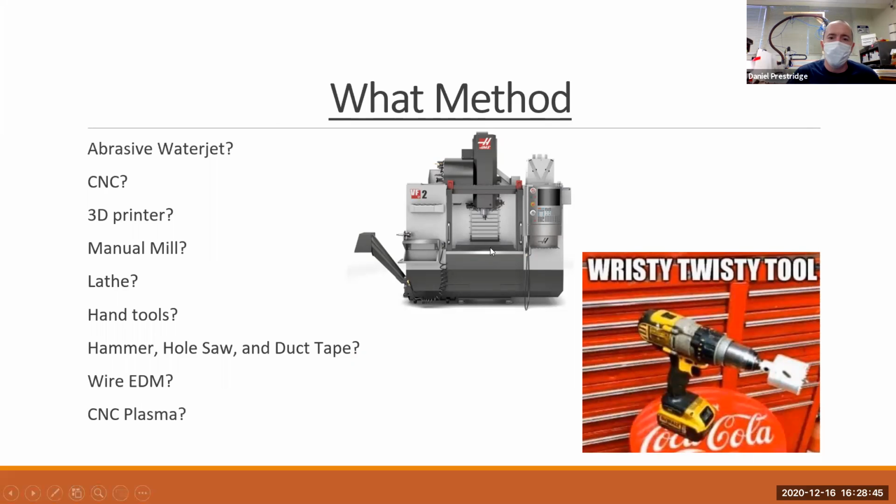And then it's going back to what method are we looking at? Are you looking at running a huge CNC? Are you doing it by hand? Are you running it in a 3D printer, manual? Are you using wire EDM? Do you have the capabilities for CNC plasma? Are you designing for somebody that has a CNC plasma setup, but maybe you outsource it to somebody else? Well, you can take those capabilities and just implement them, but don't try to do anything 3D if you're going to send it to an abrasive water jet, because that's a 2D operation.